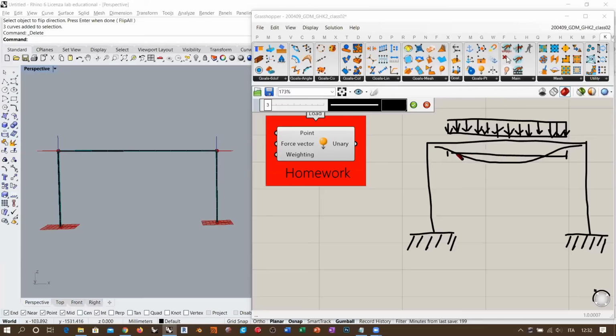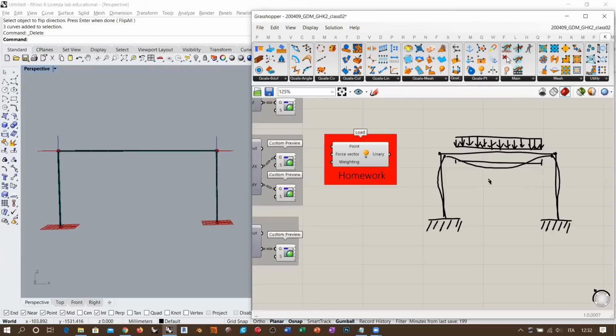It means that if it bends like this, this point should move towards the center of the beam, but also should move down a little because of the load that we have applied. And as there is no possibility for this vertex here to allow rotation, it can only move, then this movement should also create some kind of deformation like this for your columns. Okay, so this is the result that you might want to observe during the simulation.